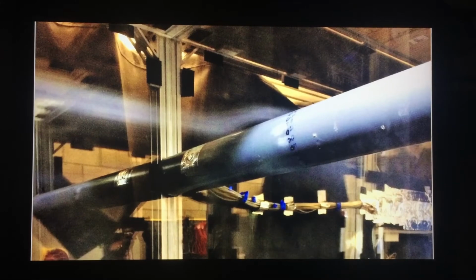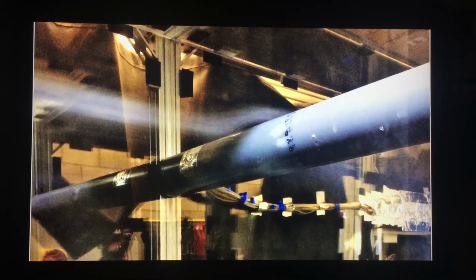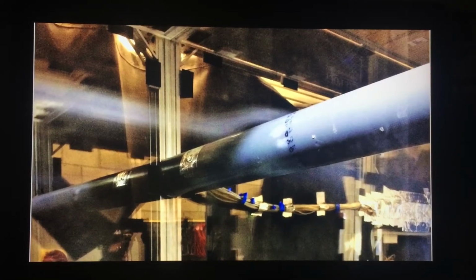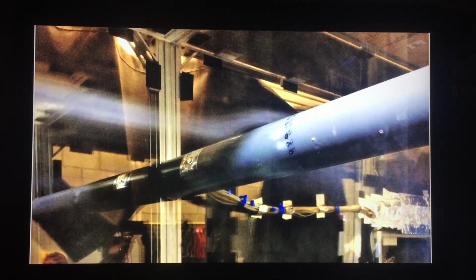The image shown on this slide is a photo which was taken during the experiment while the fan was set at 200 RPM. The airflow shown in the system is traveling over the upper half of the cylinder, and the boundary layer from the cylinder can be seen deflecting the flow from touching the cylinder surface. The boundary layer is a gap that can be seen between the flow and the cylinder body.